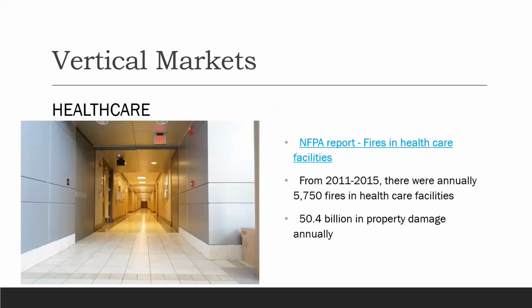Okay, so we've gone through applications now. Now we can go through those vertical markets. With cross corridor doors and the protection of elevator shafts and stairwells, we can compartmentalize that smoke migration. Remember, smoke accounts for 76% of death, damages, and injuries. A lot of healthcare facilities are going to need an up to clear 8-foot opening, and that can be achieved with pocketing and low profile hardware.